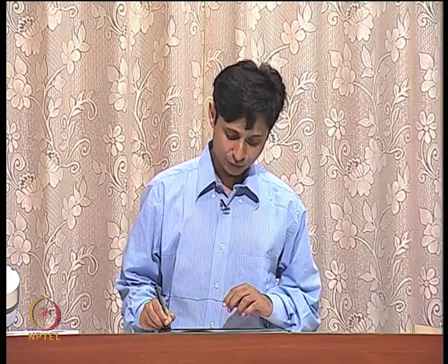Okay. So, these are some of the commonly used techniques. Use thick wires, use the topmost metal layer, use highly resistive substrate. There are a lot of other ideas with respect to inductors. See, making good inductors is very much an art. It is not really a science anymore.